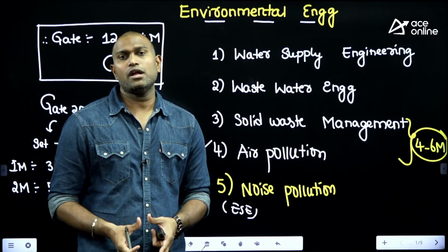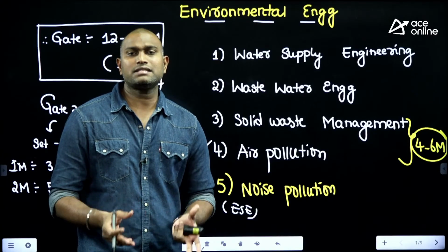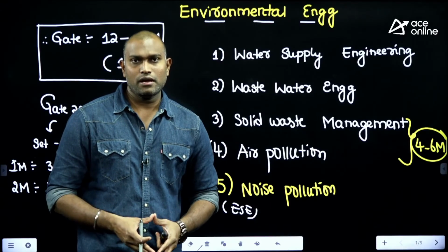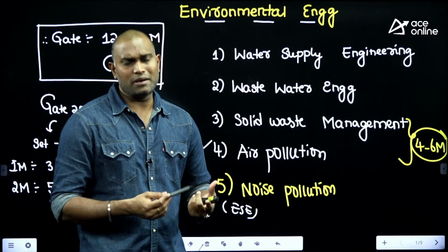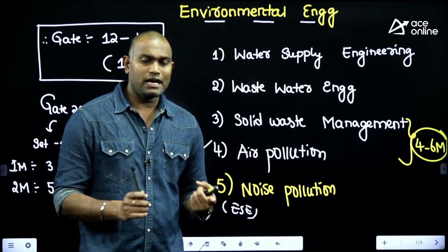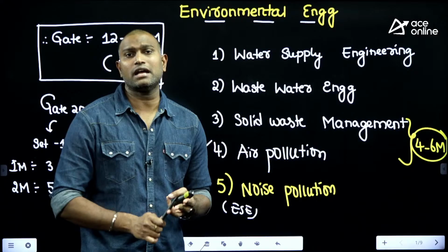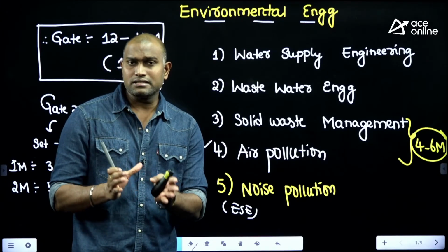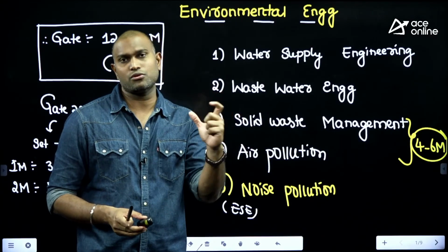We have one formula to find out the efficiency of the electrostatic precipitator. They'll be asking how many bags are required for the fabric filters. So there are control methodologies for suspended particulate matter: we have gravity settling chambers, fabric filters, electrostatic precipitators, and cyclone separators. They'll be asking certain questions. We have already formulated those things, so please go through those.